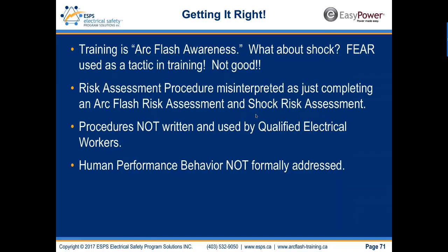So training: it's arc flash awareness, and what about shock? I see too many titles of training where it just says arc flash awareness. The word shock is not included in the title. We need to make sure that shock is in the training. Fear used as a tactic of training is not good. The risk assessment procedure is misinterpreted. Completing an arc flash risk assessment and a shock risk assessment is not the risk assessment procedure.